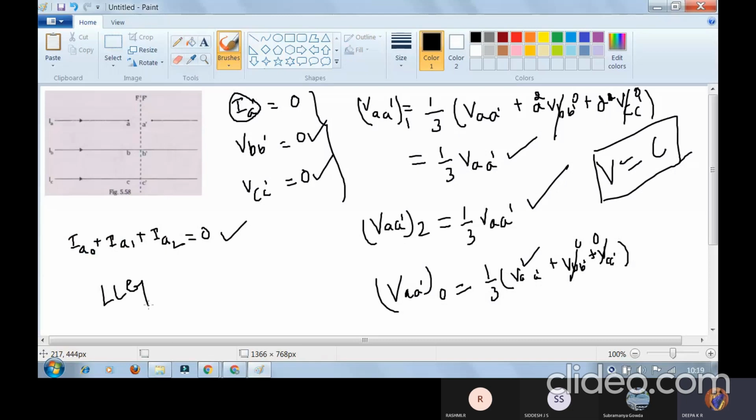So considering that, we are going to write the network. But here, voltage is constant and current is variable. In which system do we have this parallel or series network? Voltage is constant and current is variable, so branch currents will be available in a parallel network. Considering these two parameters, we have to write the sequence diagram. We are just writing the sequence diagram, not going for calculation of fault current again and again. We are just concentrating on how the network can be written for a one conductor open system.